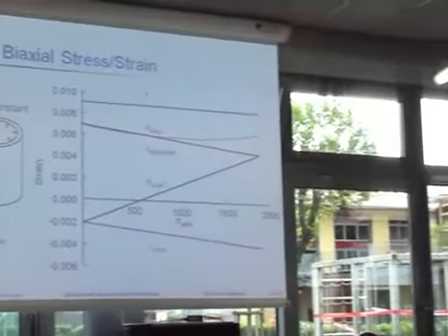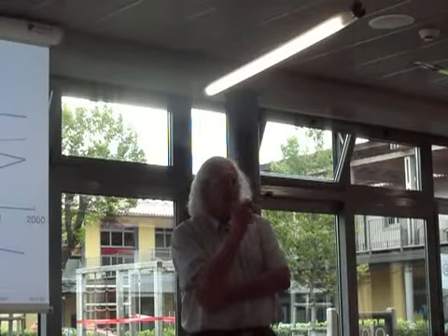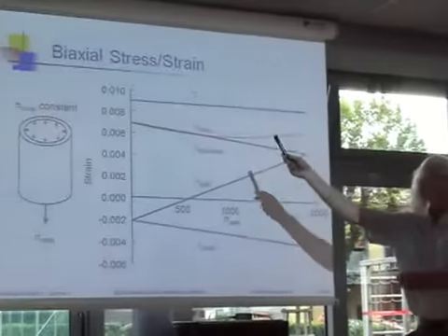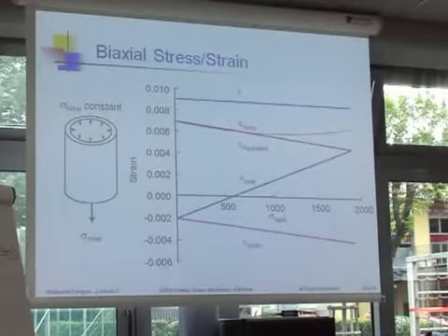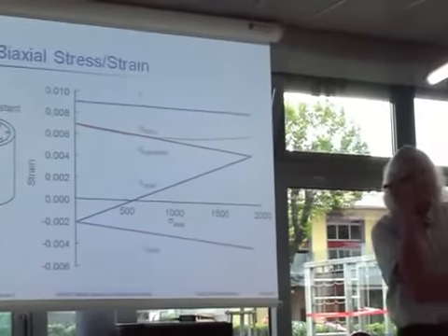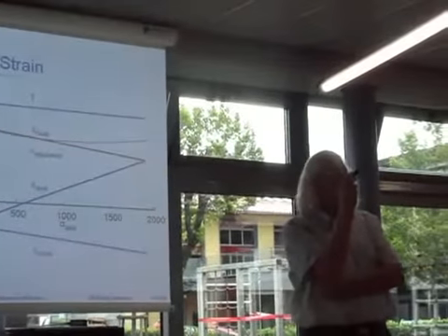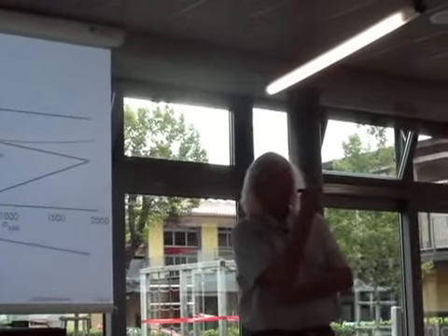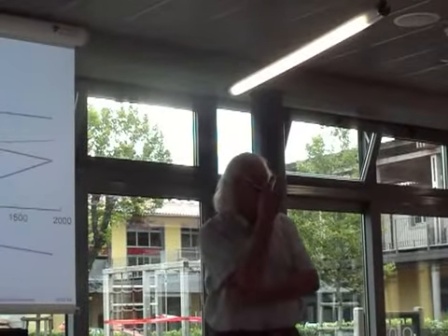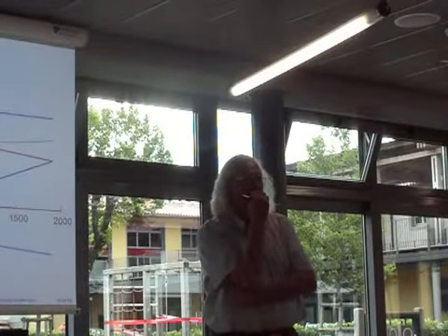By the way, this is a case where you can make a serious mistake in doing fatigue assessments if you only look at the strains, because this strain is 20% less than the other one. If I decrease the strain by 20%, how much does that affect the fatigue life? About a factor of 2, a factor of 10? How much does a 20% difference in the driving force make?